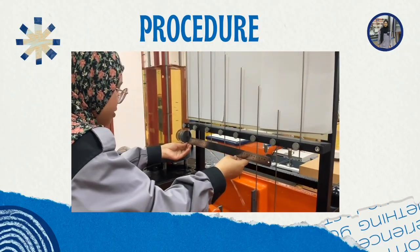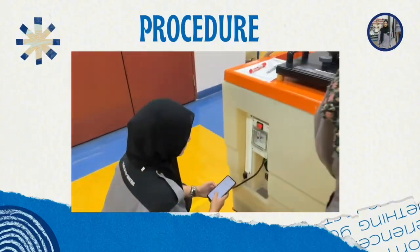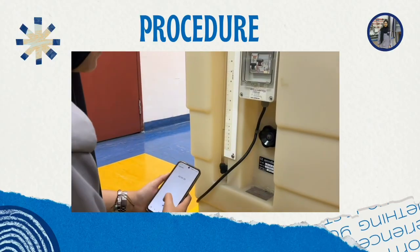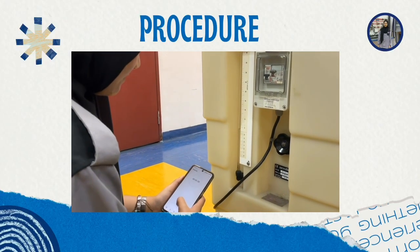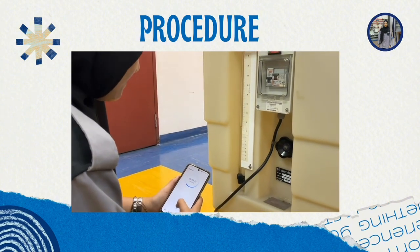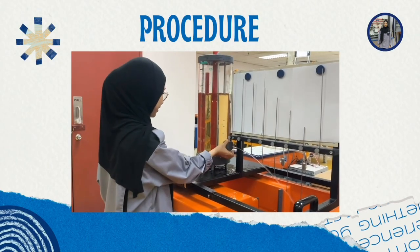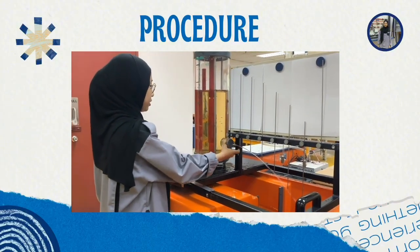Then, we measure the horizontal distance. Lastly, measure the flow rate Q at which the water exits through the orifice, and the time is recorded for each 5 liters of water. Repeat this step using the 8 mm diameter orifice.